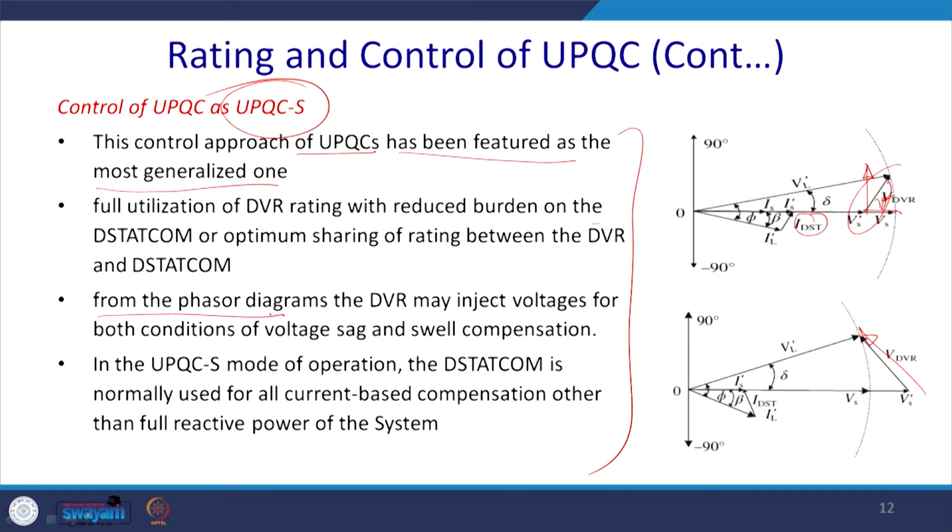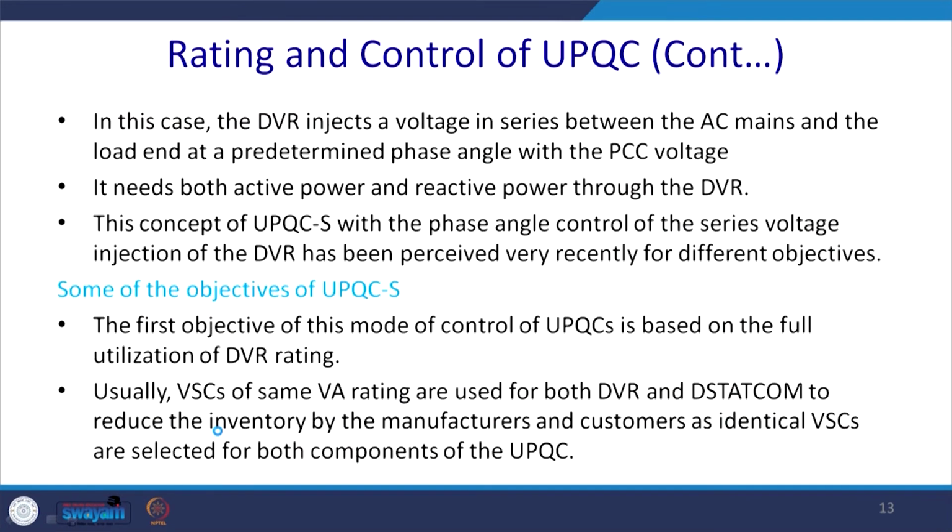From the phasor diagram of the DVR, as I explained a little earlier, the DVR may inject the voltage in both conditions, voltage sag as well as voltage swell compensation. In the UPQC S mode of operation, the D STATCOM is normally used for all current based compensation, other than the full power system compensation. So, this is the way it will work.